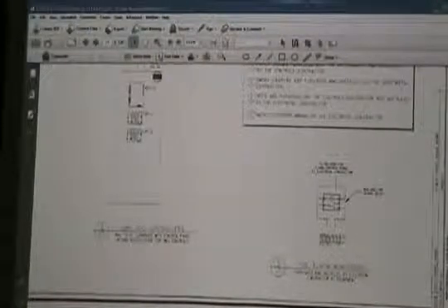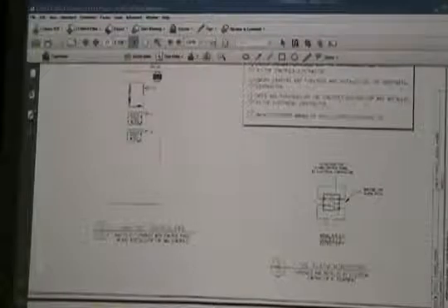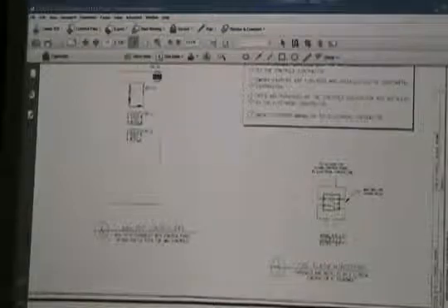There's our cabinet in the air handling unit. We've got a controller and some expansion blocks, two expansion blocks. This particular controller has a certain amount of points available on it. There's our digital inputs, our analog outputs, and our digital outputs: devices that we're controlling on and off, and devices that we're controlling with a variable signal, and the on-off signals that we're getting back into the control. And here's our analog inputs.